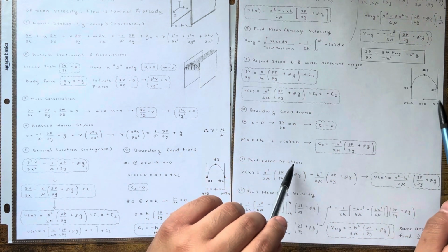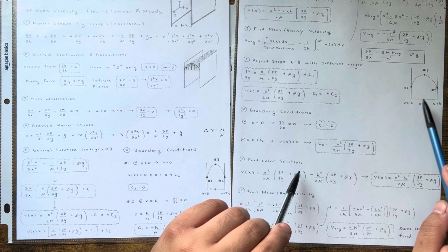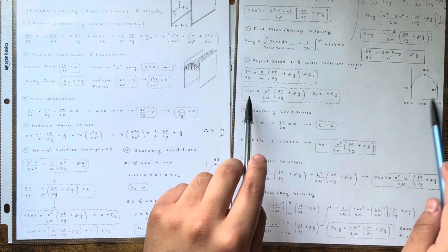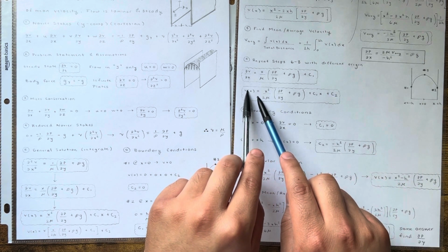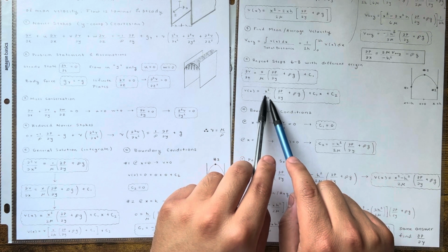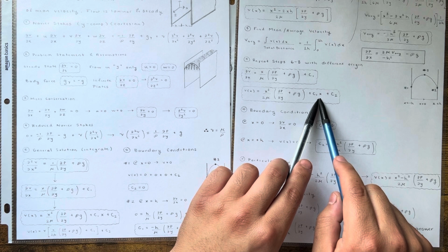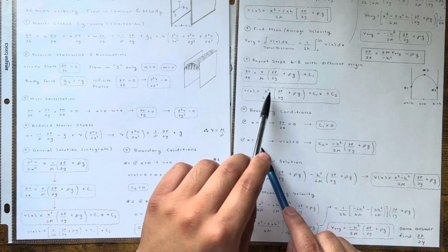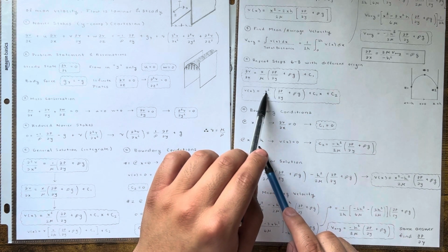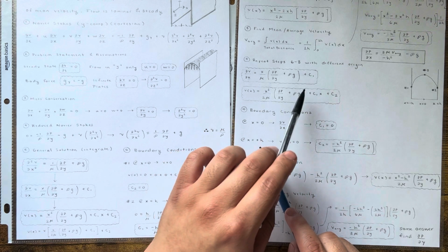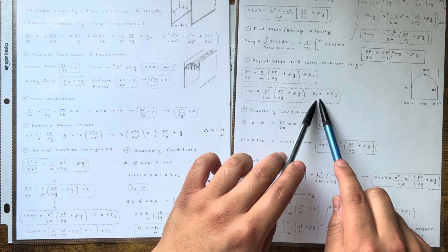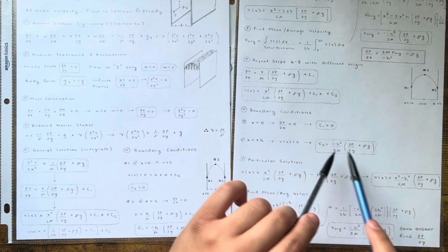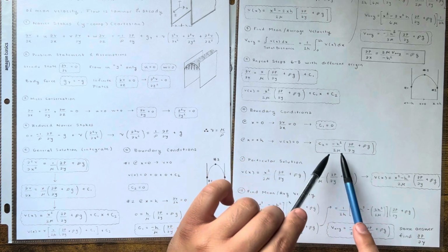Now I could use either or, and then I could say velocity is 0 at that location, okay? So in this case, I chose positive h. And when you plug in positive h for your velocity function, because this is 0, right? You plug in h. Wherever you see an x, you plug in h. So this becomes h squared over 2 mu, right? Plus c1, well, c1's already 0. So you get h squared over 2 mu plus all this, times all this, and then you just move it to the other side and solve for c2, and that's what I did.